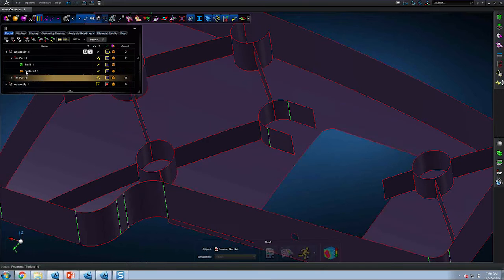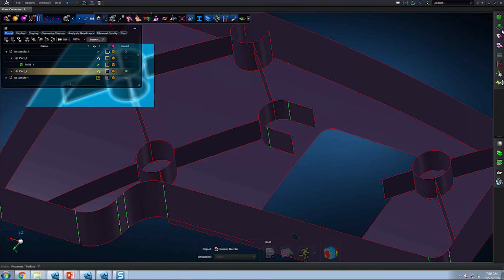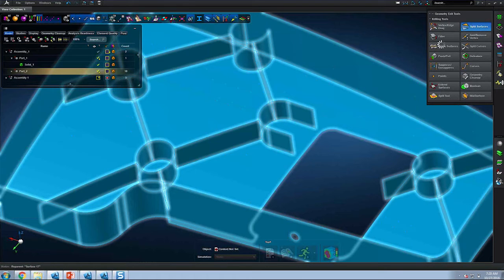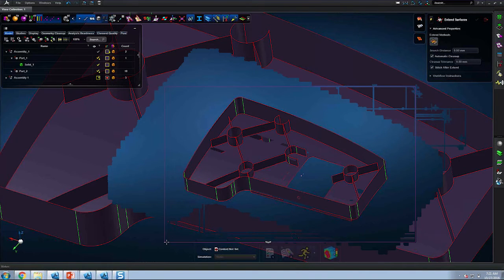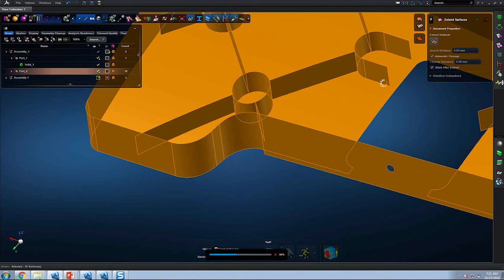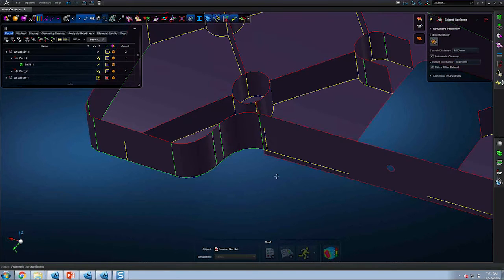Let me first drag all of these midsurface geometry pieces we created into one part. And now I'll use this extend surfaces tool that's going to allow me to extend a lot of the appropriate free edges. So free edge 1 will be extended to meet the face here. If there are coincident free edges, the application will consolidate those and make a congruent edge interface there. This is very important so you avoid duplicate nodes when you mesh. And right now we're just letting the application do this extension for us.